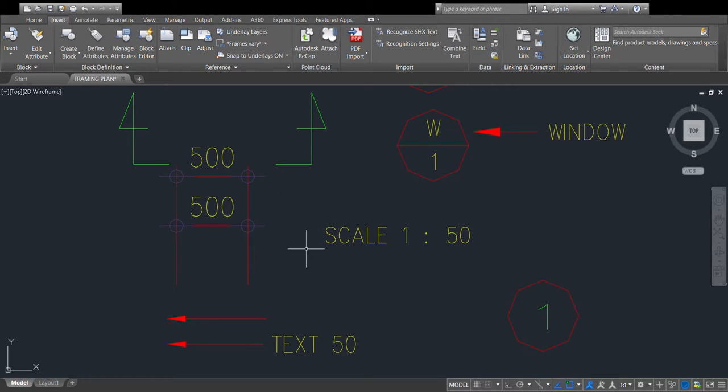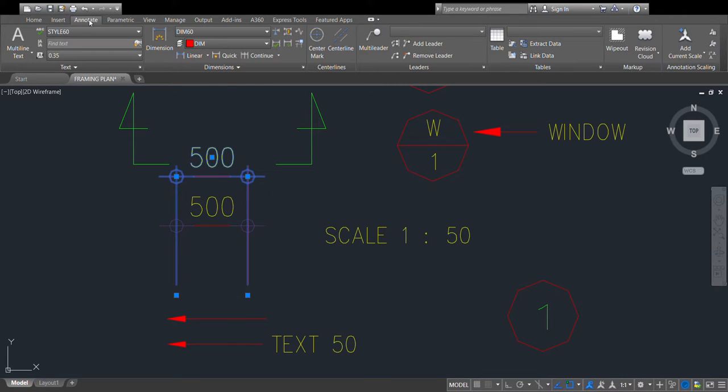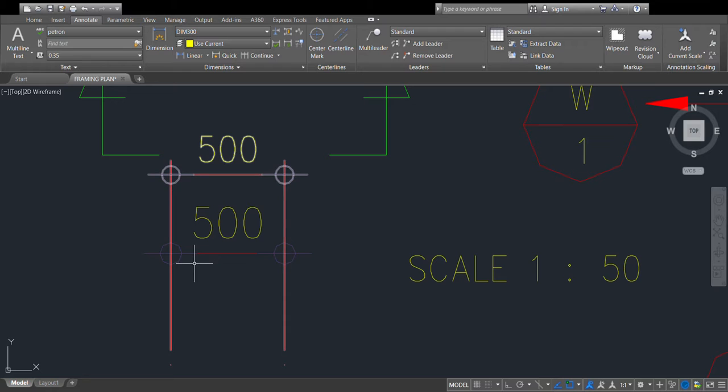Now, to address that issue, press one of them and then right click. Or you may consider this. Press one of them and then press the annotate menu. It says here it is dim 60. Well, in fact, it must be a dim 50. So look on the list for the dim 50. So what did you notice? The circle is quite smaller than the previous one.